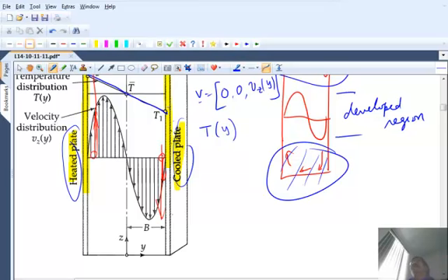Air has a thermal conductivity, just that it's very small. So we call it an insulator. But that temperature gradient will be set up in that environment also. And that means the liquid or the fluid in these regions will have different densities. But will they respond? They won't, because there is no gravity, there is no driving force. So you will not see any convection, you will not see any fluid movement.